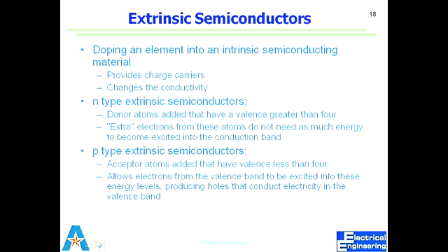So if I dope something to maybe 10 raised to power 16 and I dope another substrate with 10 raised to power 19, these numbers will become easy for you once you know what it is. If I dope it even further, the conductivity should become better for the wafer, right? Wrong. Because when we say this, we are thinking in terms of metals, which don't have any order.